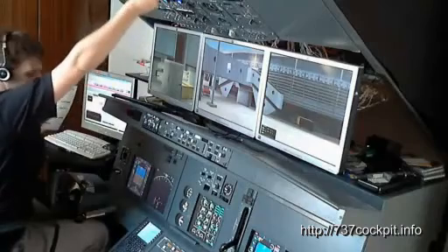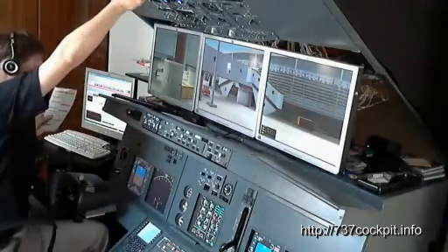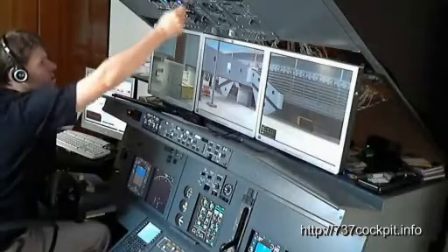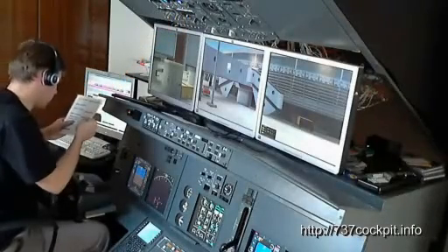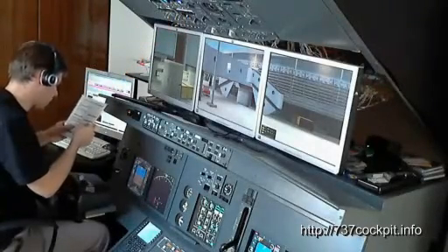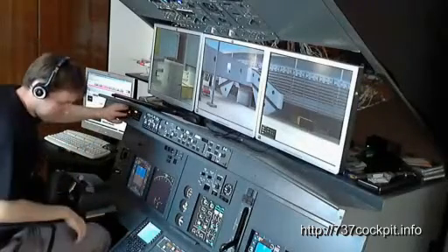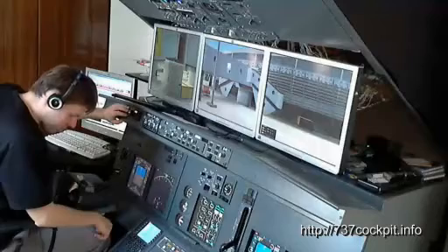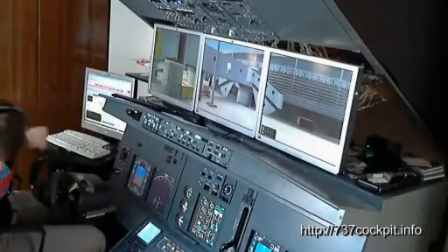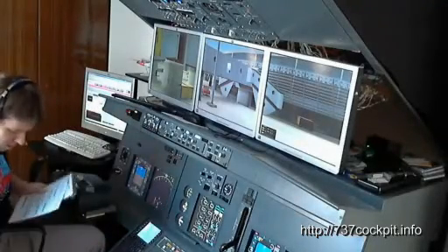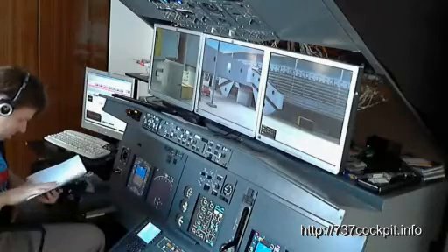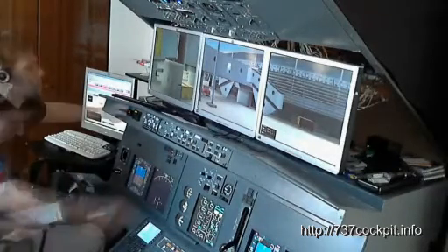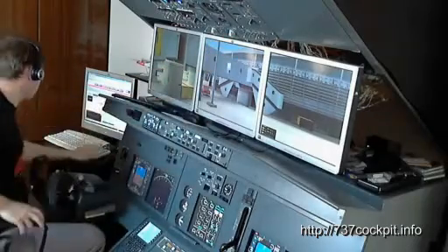Fuel flow is cut off, right engine cut off, left engine, right generator switches and left generator switches off, parking brake set, APU power on. And we have a rest fuel of 2.3 tons. And in our calculation, we have 2.5 tons, so the doors can be opened now.